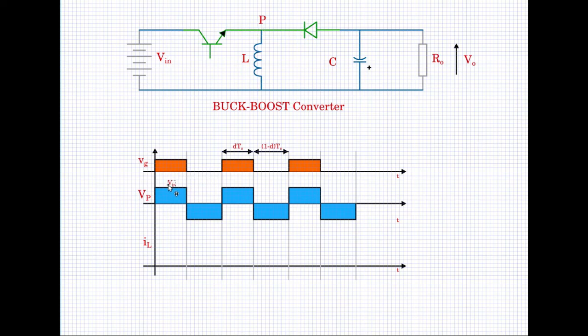Now when the BJT is on, we expect to see this amplitude to be V in amplitude coming directly here, and when this is off, diode is conducting, negative of V naught will come in here because V naught is positive at this point. So you can expect to see a minus V naught at this point. Measuring at V naught itself, you will see V naught is negative, and it will have a negative value of DC as shown here.